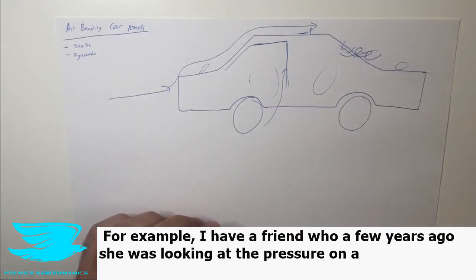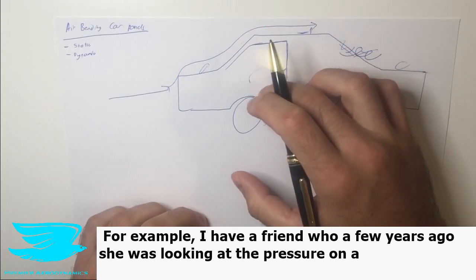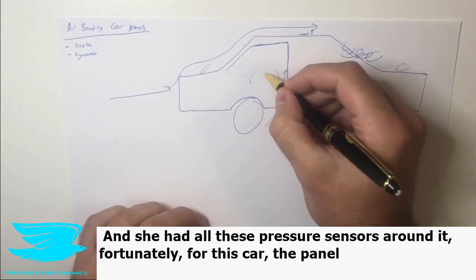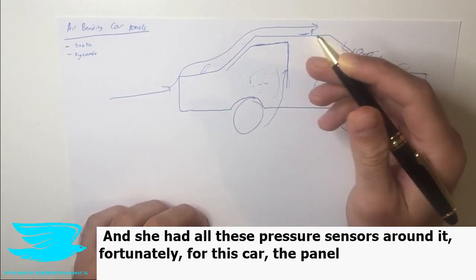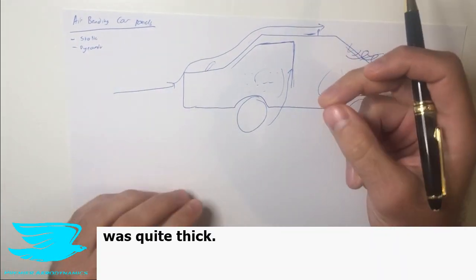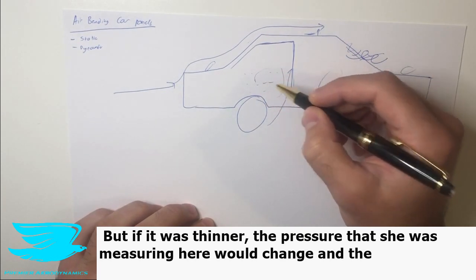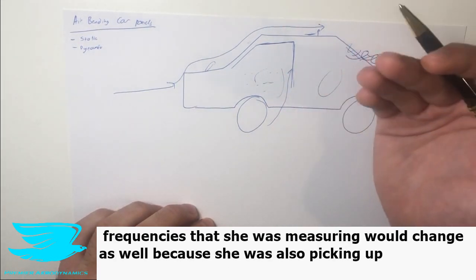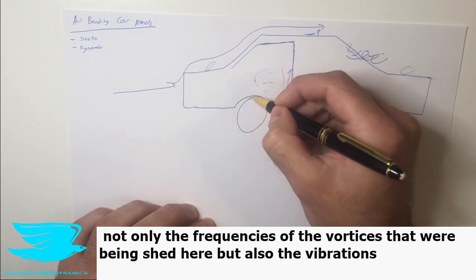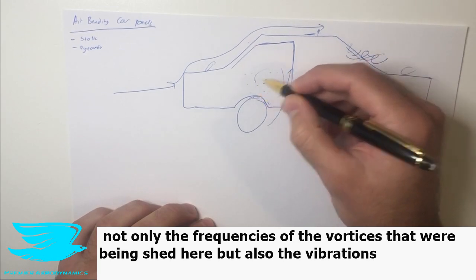For example, I have a friend who a few years ago was looking at the pressures on a door panel in particular, and she had all these pressure sensors around, and fortunately in this car the panel was quite thick, but if it was thinner, the pressure that she was measuring here would start to change, and the frequencies that she was measuring would change as well, because she would be picking up not only the frequencies of the vortices that are being shed here, but also the vortices of the door.